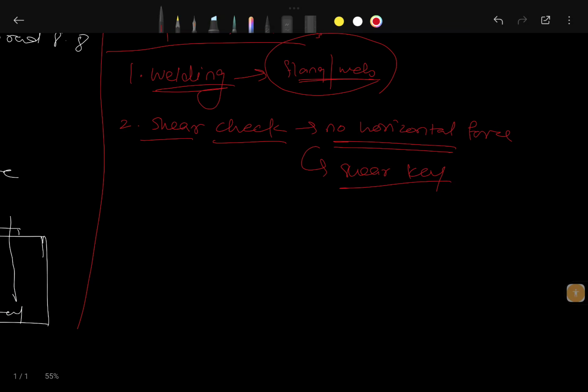Now practical detailing: the base plate will have a hole of 35 mm diameter for the anchor bolt. A washer plate is often welded under the nut. IS 800:2007 versus limit state method: this example uses the simplified working stress method for concrete bearing. A more accurate method using rigid plastic analysis of the base plate is also permitted in IS 800.